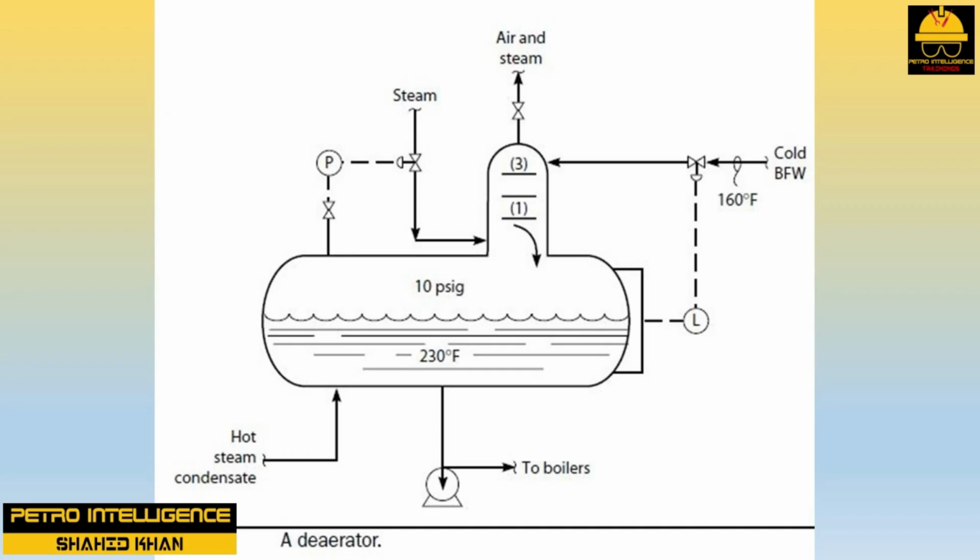Deaerator flooding. An operator reported loss of the water level in the deaerator drum. The level control valve shown in this picture would open 100%, but this drove the level down even faster. The operator reported that the only way he could restore the water level would be to mostly close the water makeup level control valve. On the surface, this story sounds crazy. But let's see what happened.